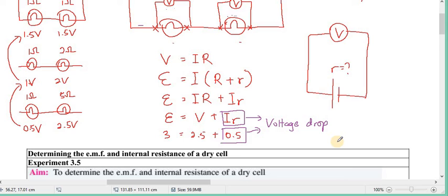So this voltage drop has gone to where? Gone to the resistance in the connecting wire. Understand or not? So the connecting wire from the switch to the fan takes 10 volt, and the remaining 230 volt is taken by the fan. Can the fan function or not?